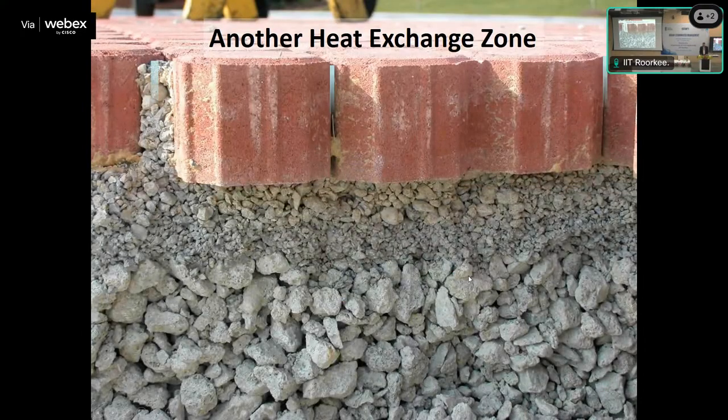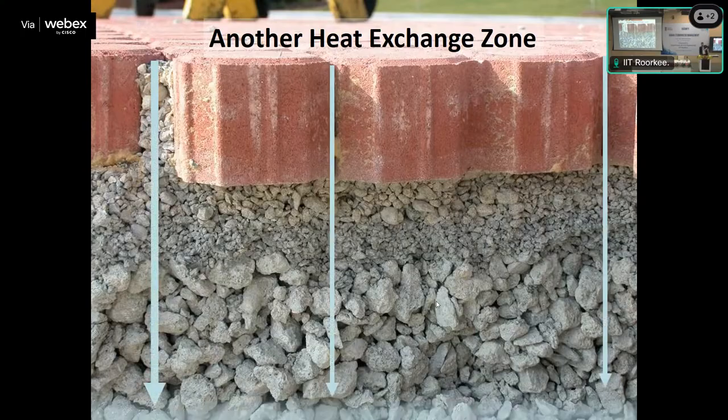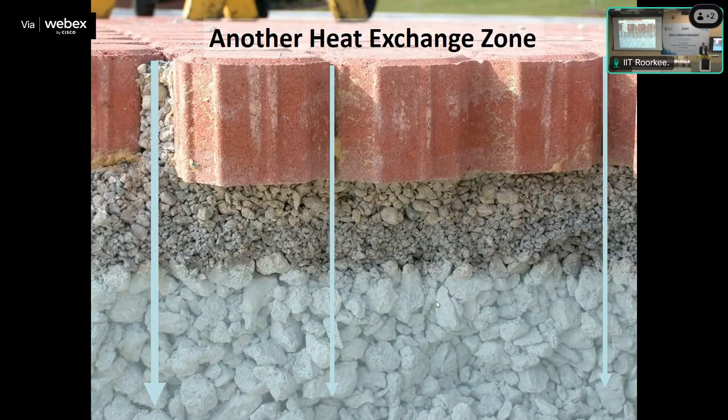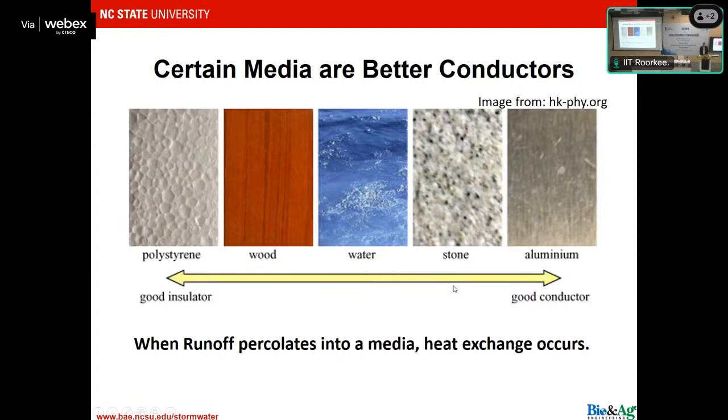Infiltration helps a lot. Permeable pavement. If you go down a third of a meter and the temperature is much cooler down there, that hot water will actually stay and mix with the cooler gravel. And when it discharges, it's much lower temperature. So all these stormwater control measures are able to cool the water down, which is particularly good.